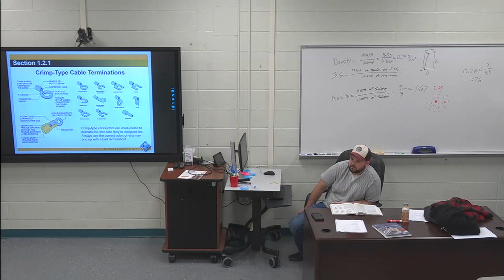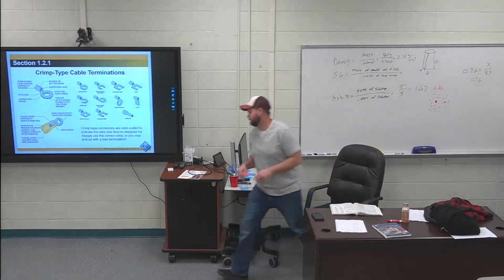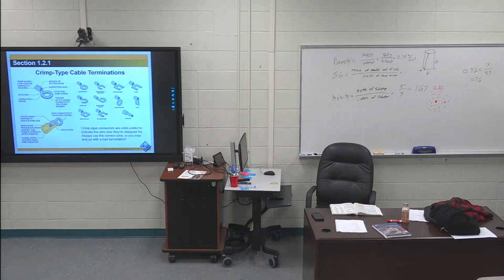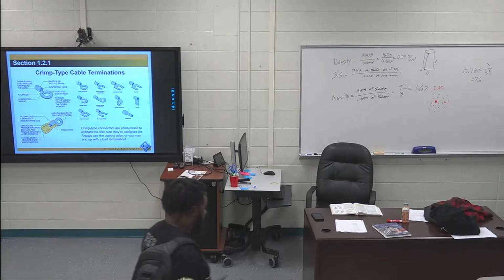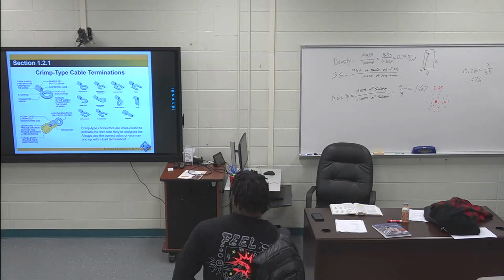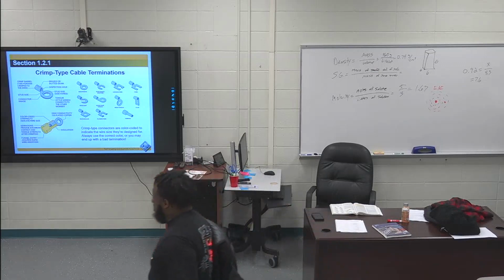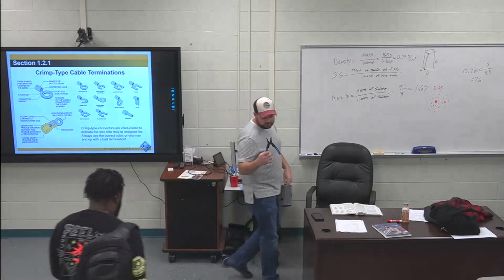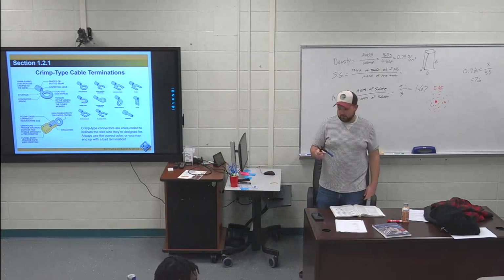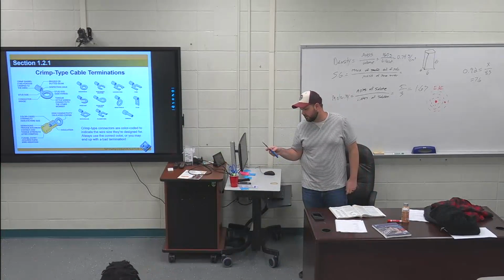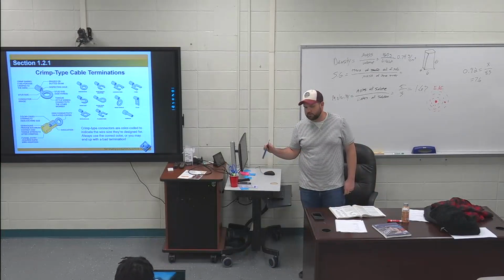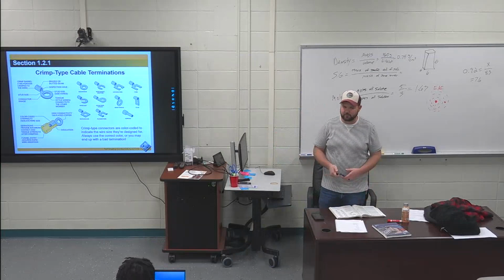I like blue handled Kleins. Those blue handled Klein wire strippers, I always have a pair of those in my bag. So like the bottom part of these is where your indentions are, that's where you do all your connections. I like these just because it has about all the wire sizes I need. It has the crimp connections, and then even if you need to, you can cut down screws. It doesn't do a great job, but you can cut down little machine screws with these.